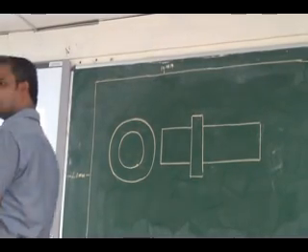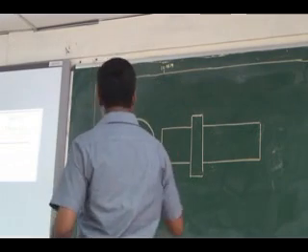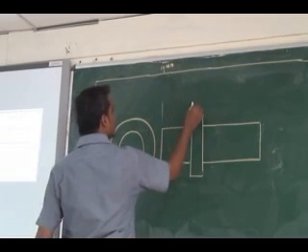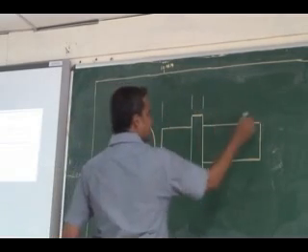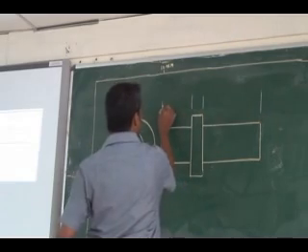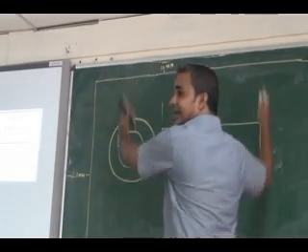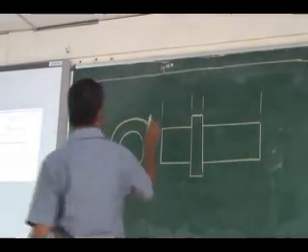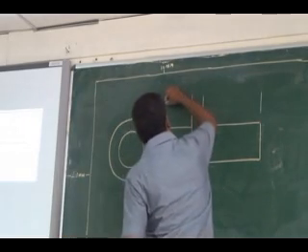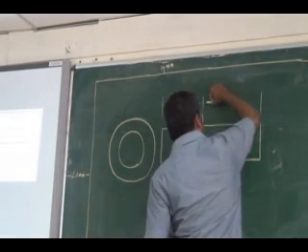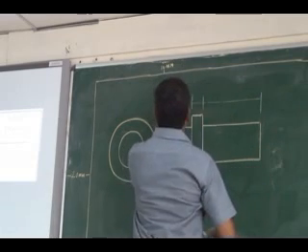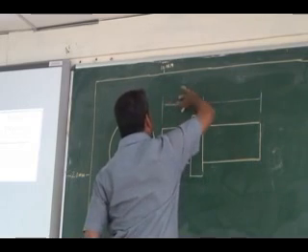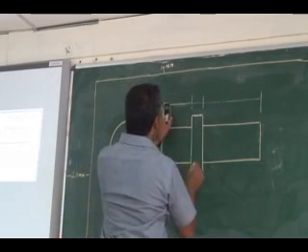Dimensioning. Suppose I am dimensioning this component, this view. I will be incorporating a few dimensions. This is called an extension line, what I have drawn here. Whatever I am drawing horizontally, parallel to the entity which you are dimensioning, that is called the dimension line.